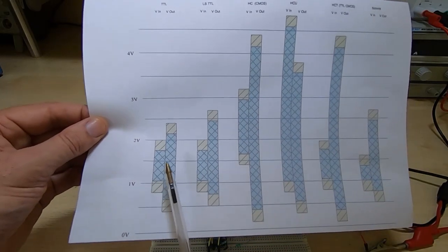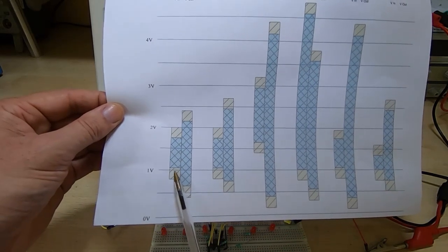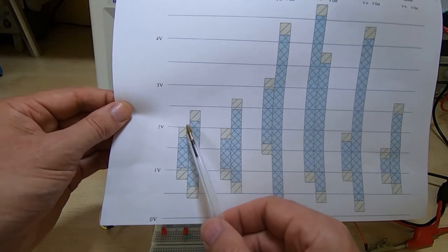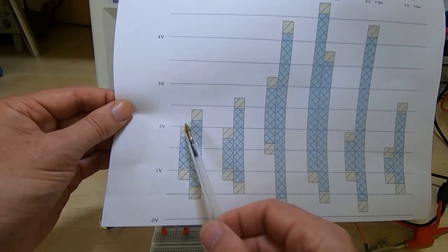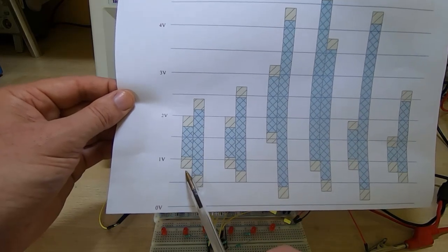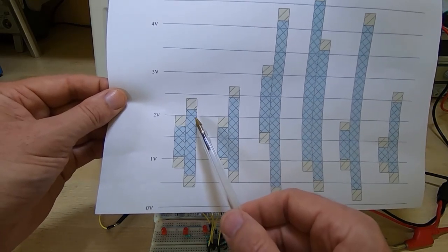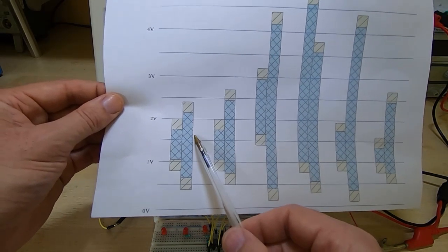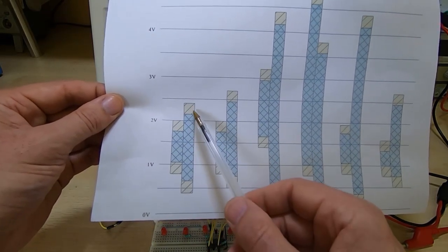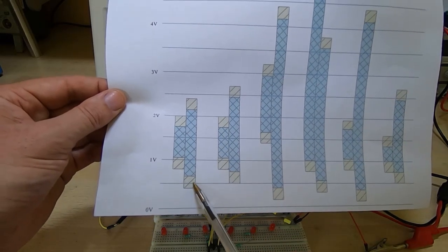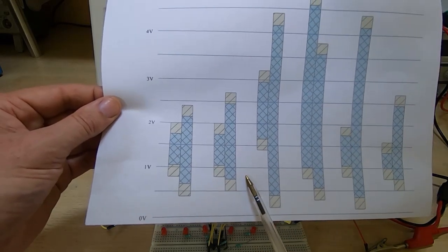So what we've got is a standard TTL, and you can see that on this chart the left hand bar is the input voltage range, so anything above the top of this bar is an acceptable range for a high input, and anything below is an acceptable range for the low input. And then the output bar is the expected output driving nominal loads, and the different coloured areas at the ends assume a 100 millivolt degree of uncertainty, which is quite small. Normally it's far greater than that, but I'm trying to keep this as a fairly practical example.